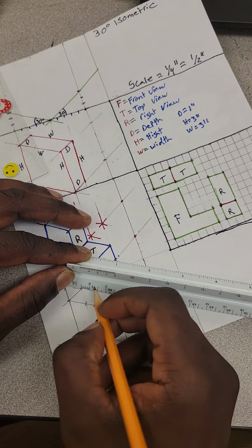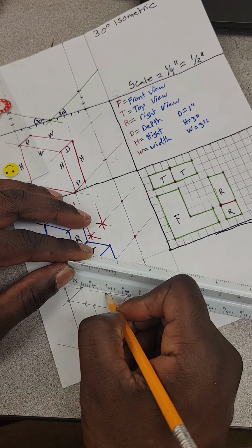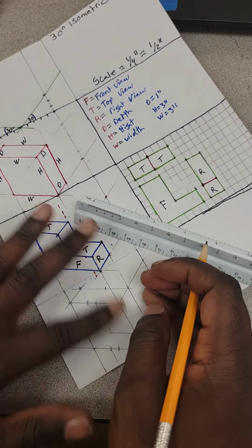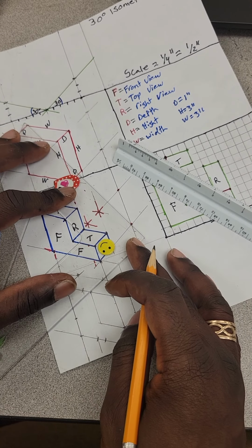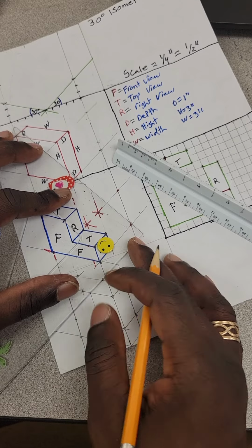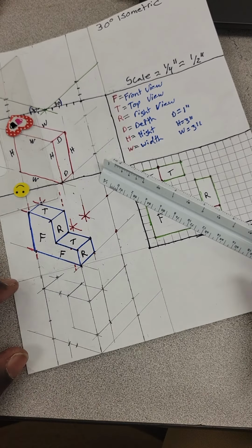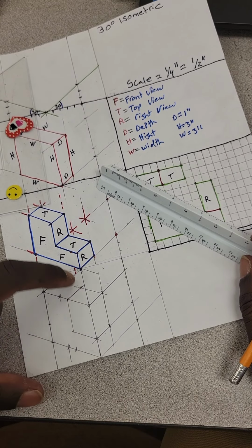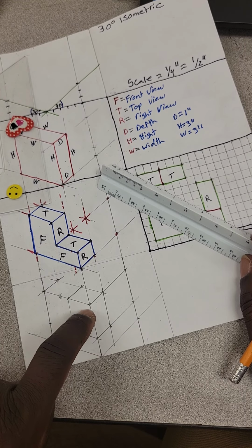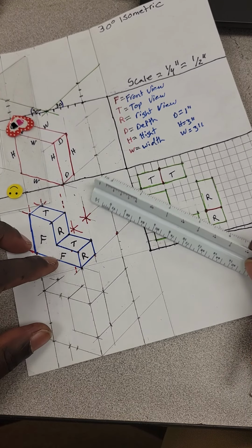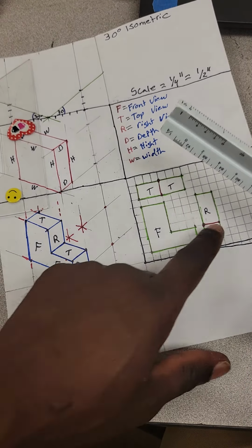So then come down 1.5 inches because we know that's how long this box is. This is right here. That's why I said don't jump around, because when you start jumping around is when you get lost, and you didn't leave cookie crumbs to go back. So we're at this point now, and we need to get this point in the back to connect this down to and that across. So what we're going to do is come down 1 inch and then connect this to this. Why go 1 inch? Because our depth is 1 inch.